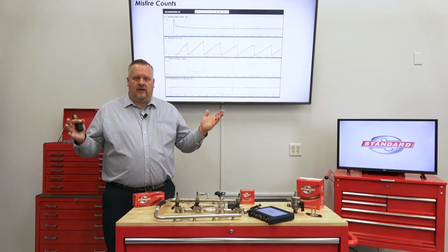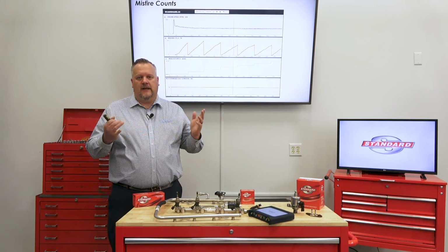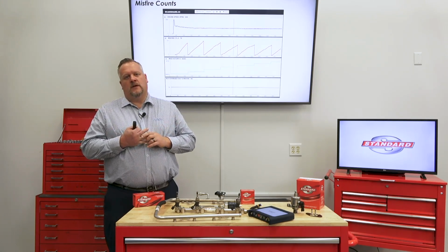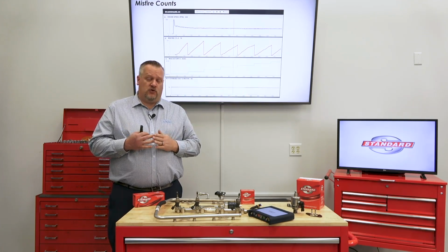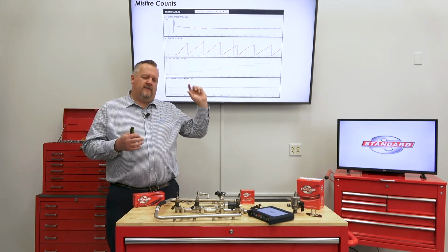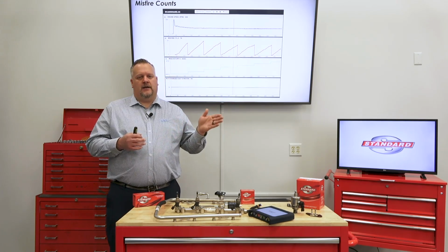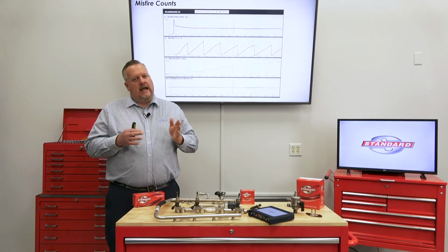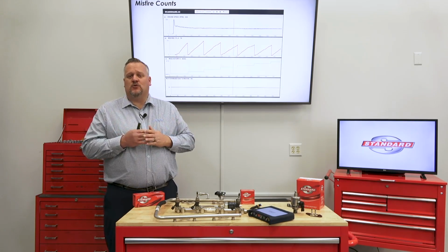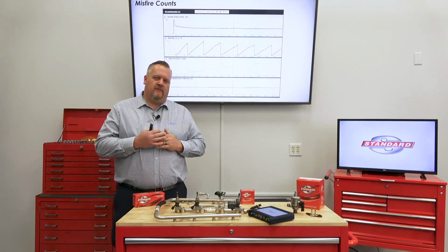Now, it could be a mechanical issue, could be a leaking valve of some sort. We can go down that path for sure, but knowing that we've got a fuel trim issue as well as an on-idle issue here, I'm kind of thinking a little bit, and this technician was as well, a little bit down the fuel delivery path.